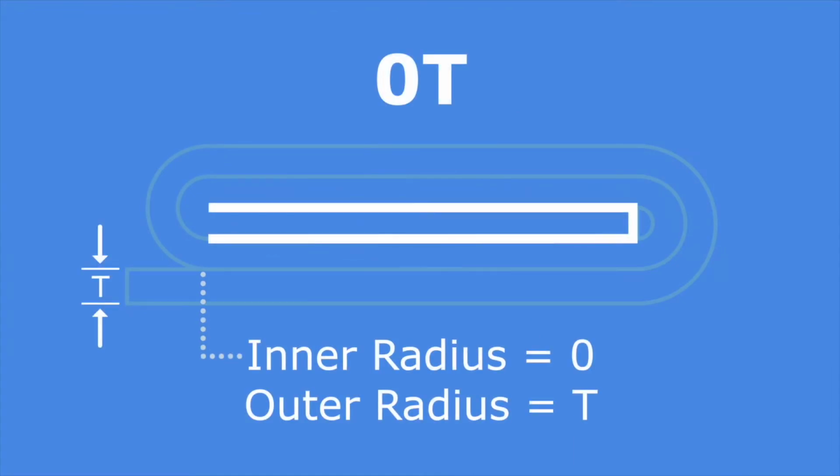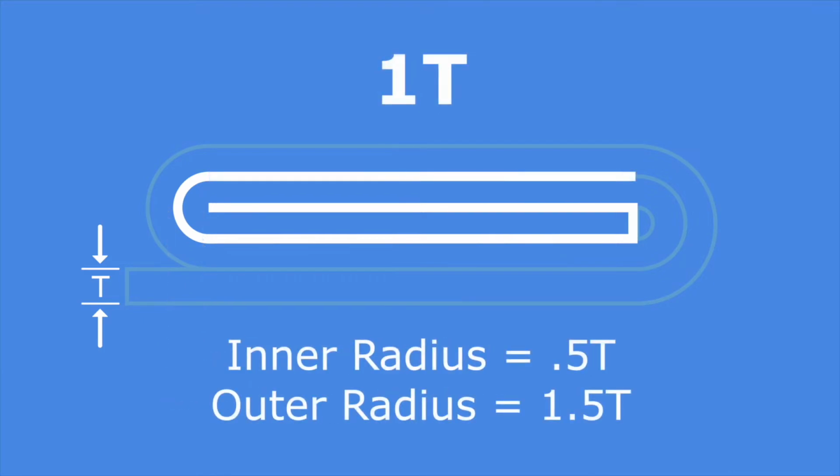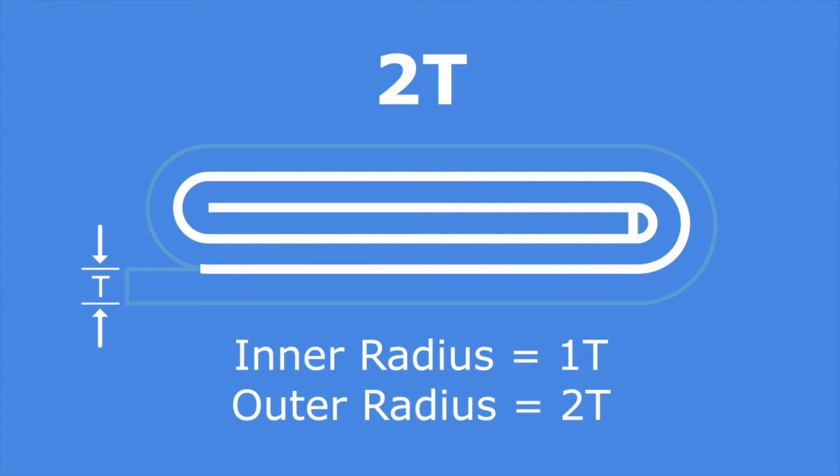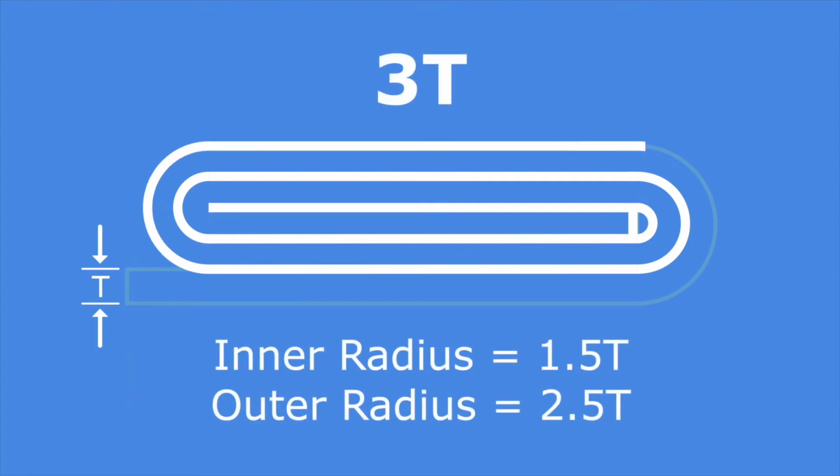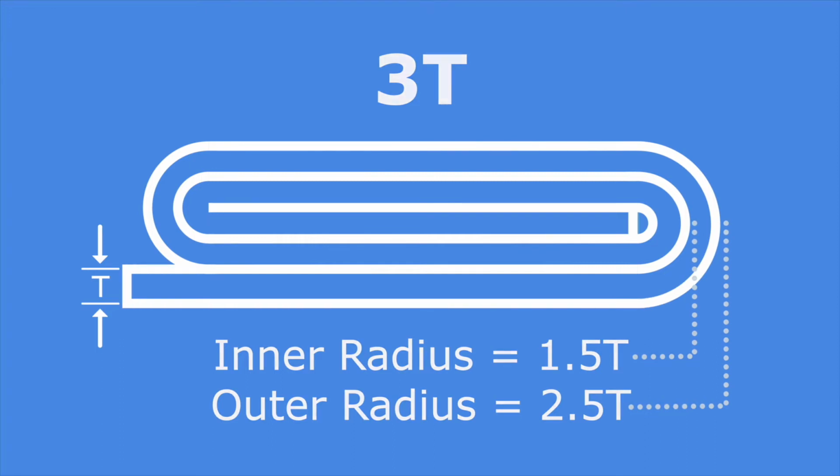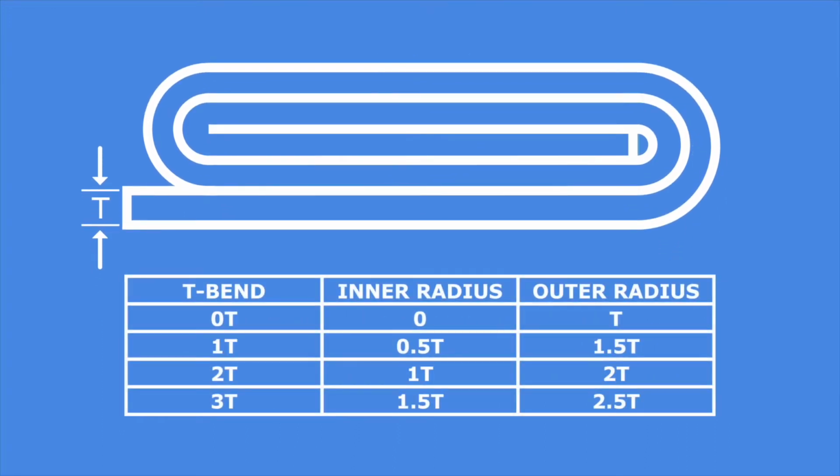When testing the flexibility of pre-painted metal, a T-bend test is routinely done. The key to understanding what is happening to the coated metal is knowing the inner radii of the bend. In a roll-forming operation, each bend has been designed with a known inner radii. The figure below shows typical T-bends using NCCA nomenclature, where T is the thickness of the metal. The inner and outer bend radii are shown in the table below.